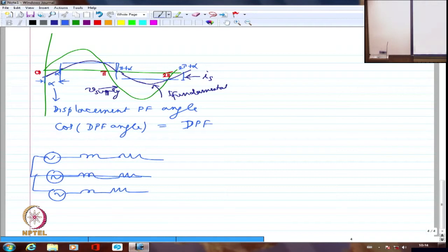And if I have harmonic currents and if I have R and L, multiplied by the harmonic current will give me the harmonic voltage drops. So although I generated sinusoid, now I'm going to have some harmonic voltages, maybe negative, maybe positive, whatever, that is generated in the transmission lines, which is ultimately going to reach the motors and so on, which I'm connecting in the power grid.